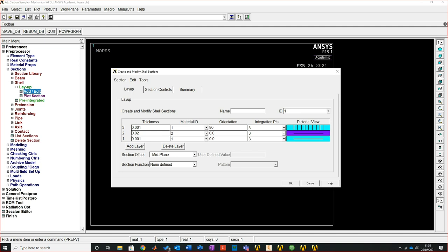When it's to extrude the actual process, which way does it go and how does it do it? If you look here, we have mid plane, bottom plane, user input location. You can actually define. I always leave it as mid plane in this case. From anybody's perspective, you can think if it's 10 millimeters, it will be 5 plus or minus to give you that type of an offset. So that's how this one is laid at the moment. You can change that. More than happy for you to change that.